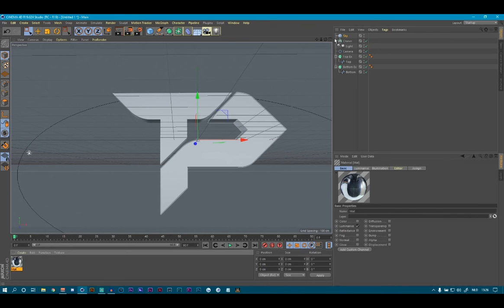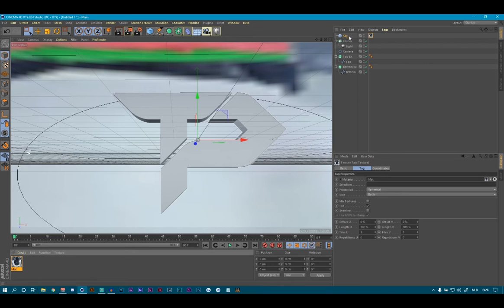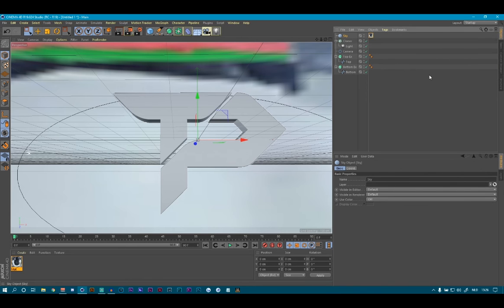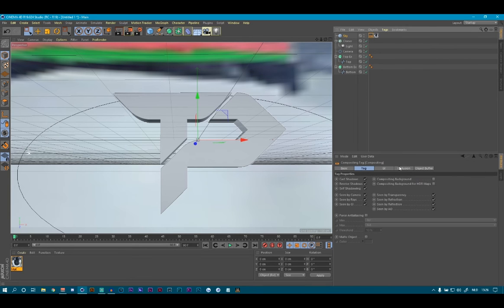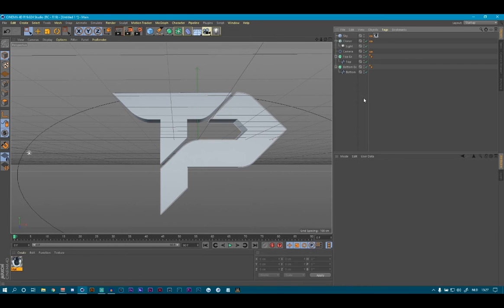We're going to go ahead and drag that onto our sky. Now, the important thing you want to do, right click on your sky, go under Cinema 4D tags, compositing. Compositing is your best friend. Seen by camera, uncheck it. Now, hold the control button, drag that to your cloner, drag that to your camera, and now nothing is going to be seen except for your logo.